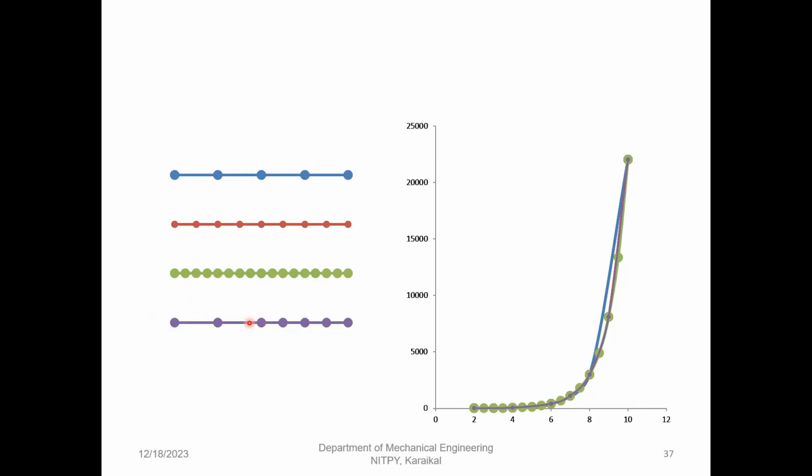To know where there's going to be gradient or not, you must understand the physics of the problem. So if you have a flow past a cylinder, you're going to be interested in the dynamics happening after the cylinder. If you're interested in supersonic flows, where the shocks are going to happen, that is your region of interest. So depending on the problem, you have to find a region of interest and put more cells in that region. That will help you in getting your solution faster.